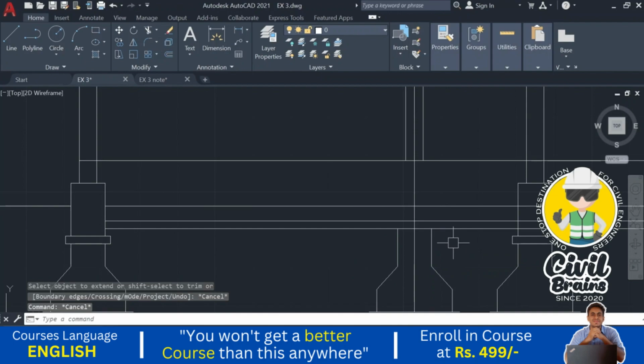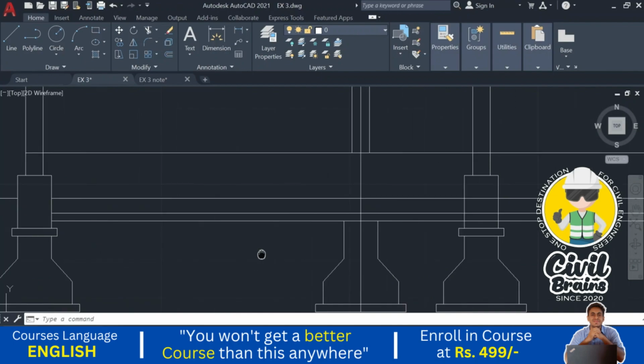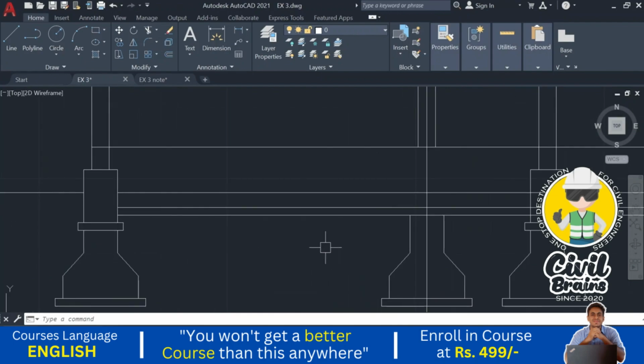So what is the width of the foundation we have considered here? We have considered the width of the foundation here is 0.3, that is the width of the wall masonry foundation, and width of the trench we have considered here, that is 0.5 only.